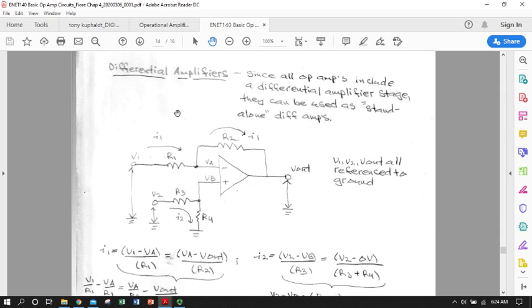Okay, the last individual type of amplifier that we're going to go over is the differential amplifier. This really should sound familiar because we went through the discrete components that could make up a differential amplifier right at the beginning of the course in chapter 1. So we actually made a differential amplifier out of a series of BJTs and biasing resistors. And then we went on to say that every op-amp, every operational amplifier, regardless of the package that it had or its performance characteristics, usually had a differential amplifier stage or section for its front end.